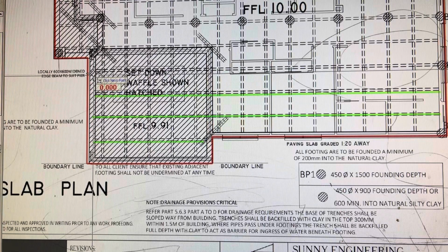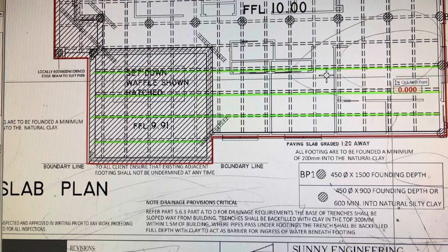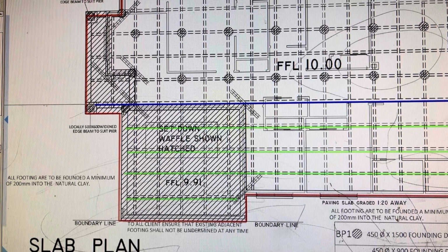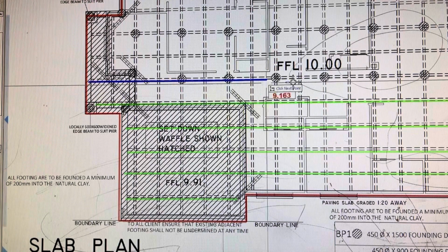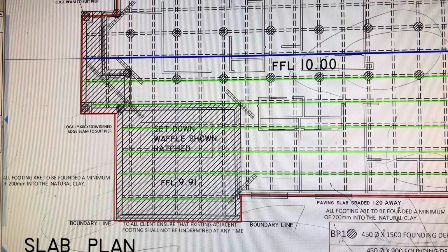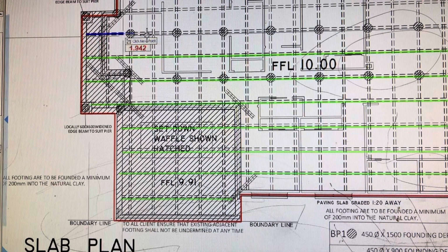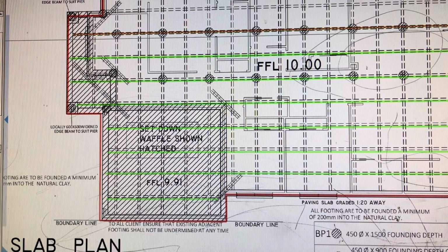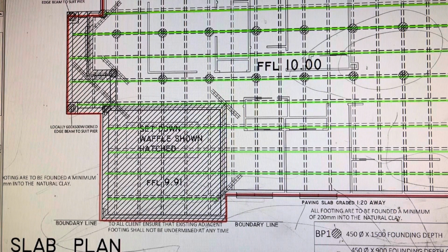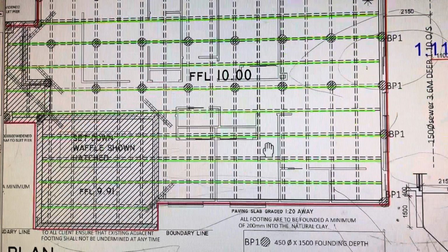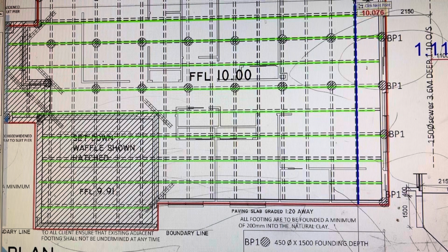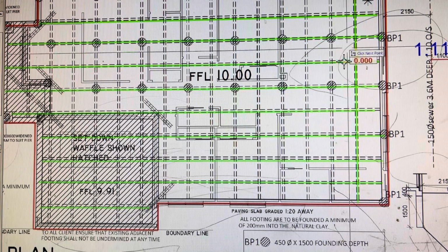so that we do it in a systematic way and don't get confused about what we have done, what we have missed. So you cover all horizontal first and then vertical, or vice versa, as long as you have a system, because you want to do it in a very systematic way. Otherwise it can be very confusing for complex commercial jobs. If you're not systematic, you can miss a lot of quantities, and every quantity can be thousands of dollars.